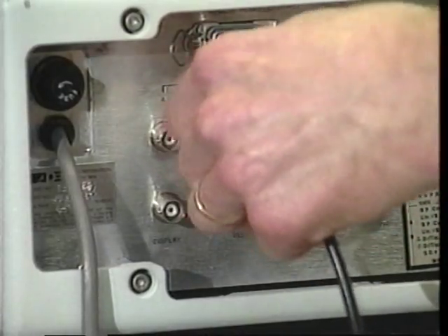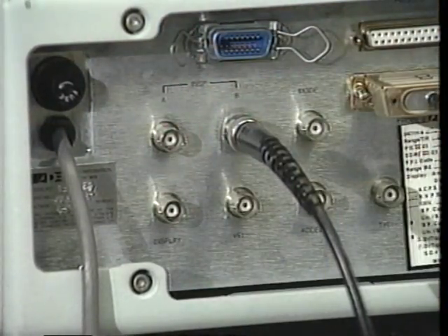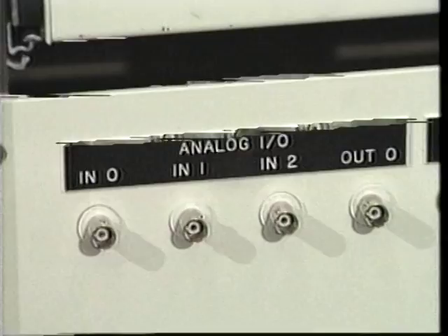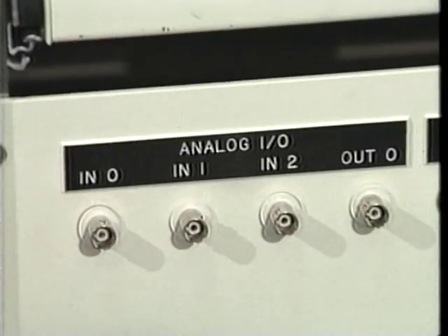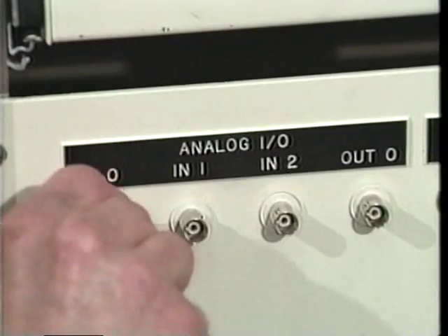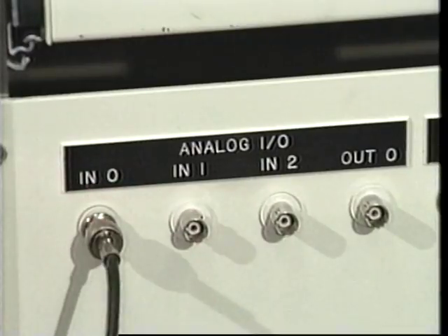The analog voltage signal from the capacitance gauge will be sent to an analog input on the diamond turning machine's controller. Inside the DTM controller, the analog signal will be converted to digital values. The DTM controller, which has resident data gathering routines, will record the X and Z axis positions and the digital signal voltages. Later, these voltages will be converted to distances using the scaling factor of 2.5 micrometers per volt.